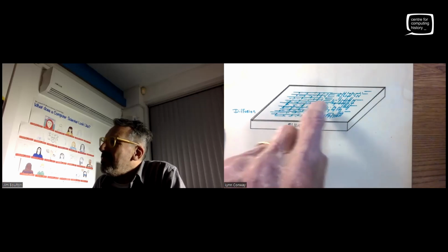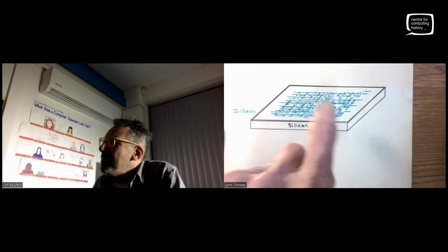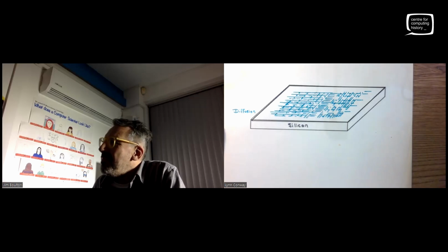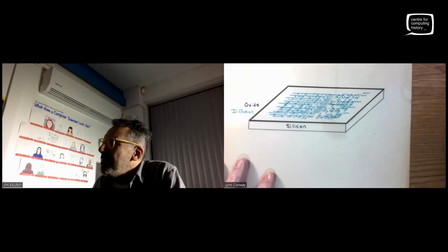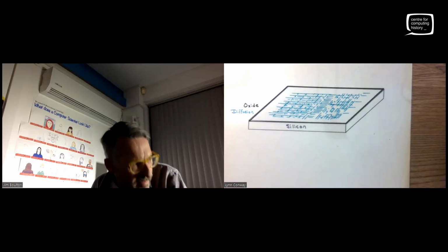And we use a computer, using design rules, to create the patterns in a digital form so we can easily make the mask to do it. Then what we do is we put a layer of silicon dioxide. It's an insulator. It's kind of like we're making a little printed circuit board. And if you look at that now, you wonder, okay, all we have is wires and some insulator. That is kind of like a printed circuit board, isn't it?